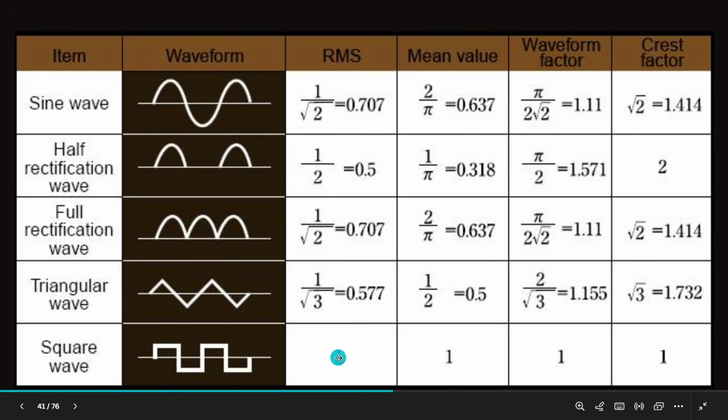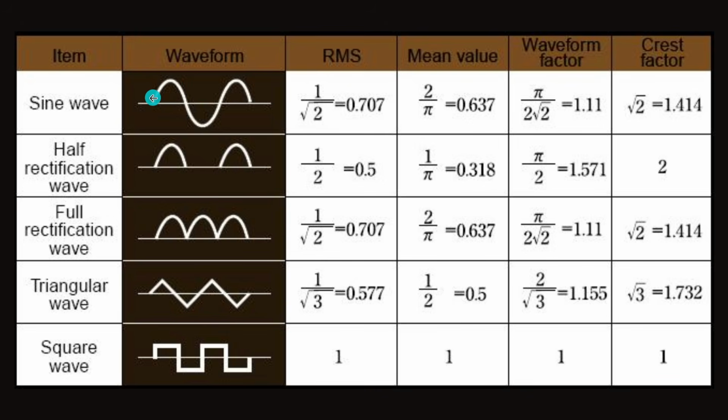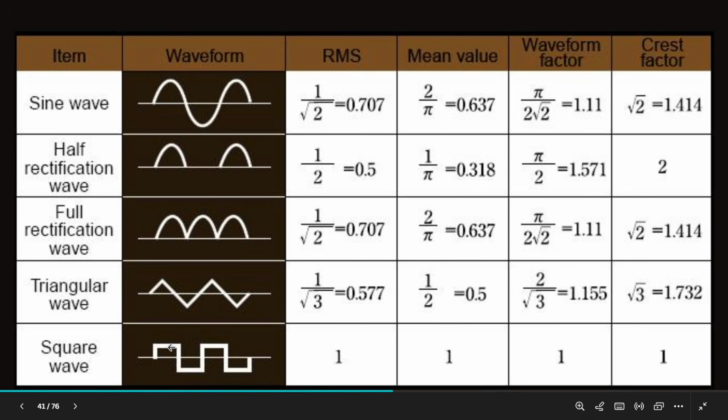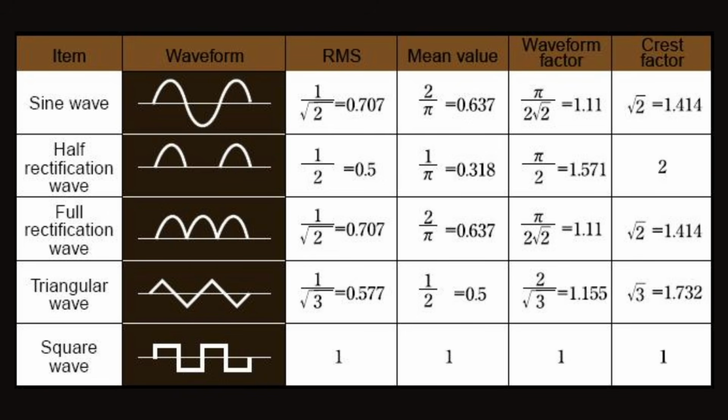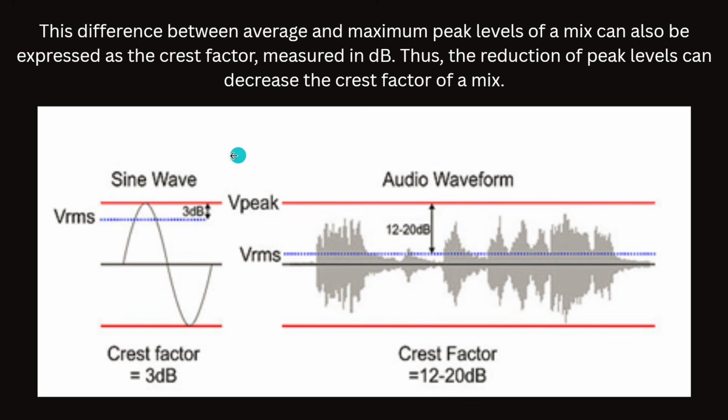It's the highest one. And you can imagine when we start clipping a sine wave, it becomes more and more similar to a square wave. That means you will get far more heat from a sine wave when it's at the clipping level. And this is why when we are running amplifiers at the clipping level, they overheat. Either the protection kicks in or they will burn. So we need sufficient power that we never hit clipping. And here I want to draw your attention to a difference between a sine wave and a real audio signal.